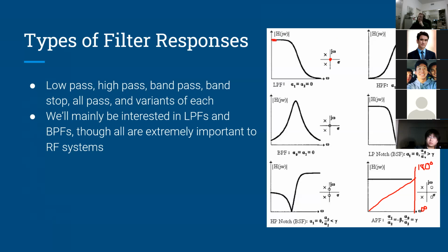So when we're at DC, we're passing signal. And then as we move up in frequency this direction, at some point we start moving away from both of the poles. And at that point, there's no longer any poles propping up the frequency response. And that's when this curve starts moving down. And then as we go to infinite frequency, eventually it goes to 0.